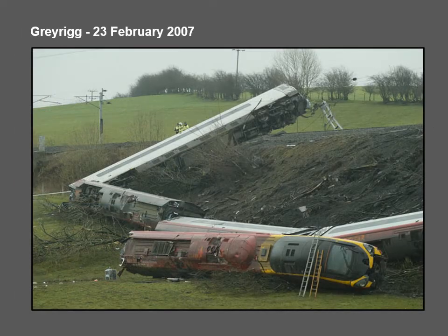If you go back to the Greyrigg accident report of 2007, we can see that the train performed better than earlier designs in previous accidents. The passenger and crew areas were not significantly compromised. However, only 2 windows did not fully retain people within the carriages. The bogies also did not separate from the carriage bodies. However, the RAIB considered that safety could be improved in relation to the design of seat mountings and the lighting panels above the seats. And these were associated with recommendations for the study of rail vehicles and rollover.